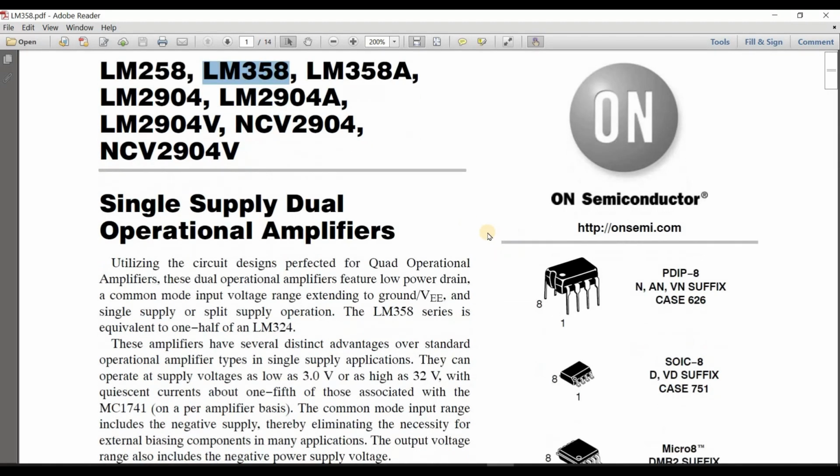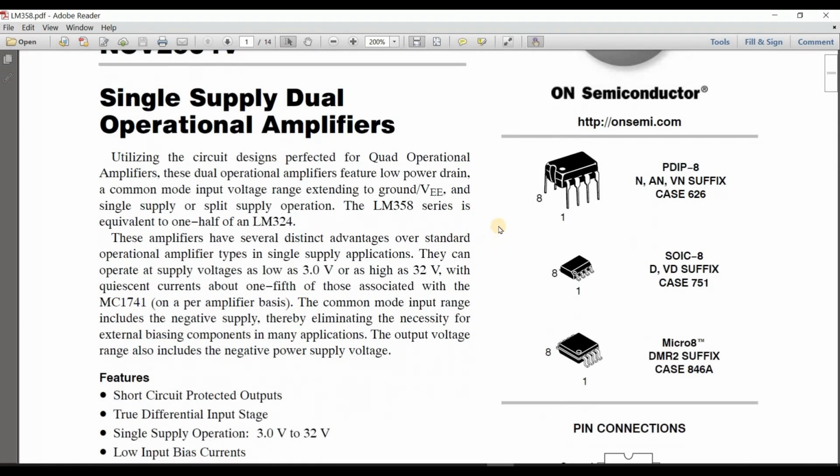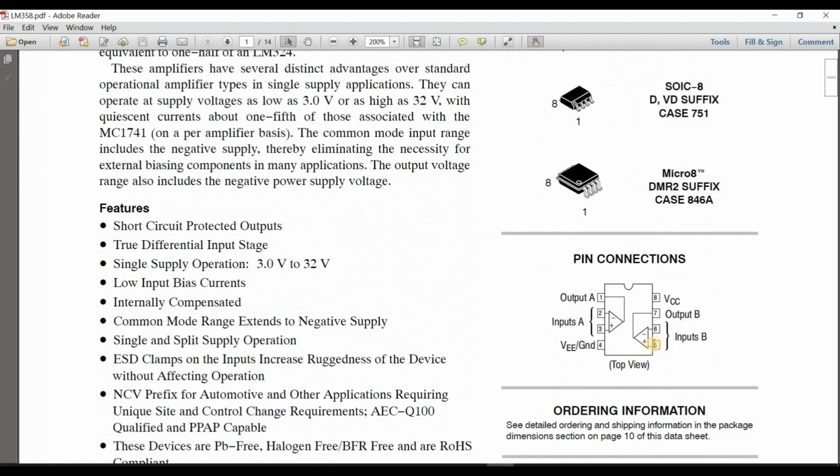It's a really popular amplifier, or actually it's a dual amp. If you can see the inner construction of the IC, it's got two op amps where we can use it to buffer two signals. If, let's say, we have two PWM signals, after we filter them out, we can use this one IC to buffer two signals.